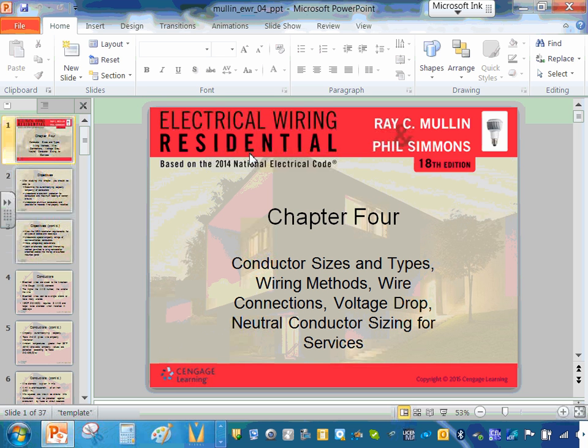So the inspector, when they walk in, this is supposed to be in the kitchen. 2 of these are supposed to be in the kitchen. Look at how easy it is for the inspector. Walk into the kitchen. If he doesn't see this color, you're doomed. Just by walking in the kitchen and looking, do I see this color? Yep. Then I'll go check. If I don't see this color at all, then where are your 20 amp circuits in the kitchen? See how they make it easy?